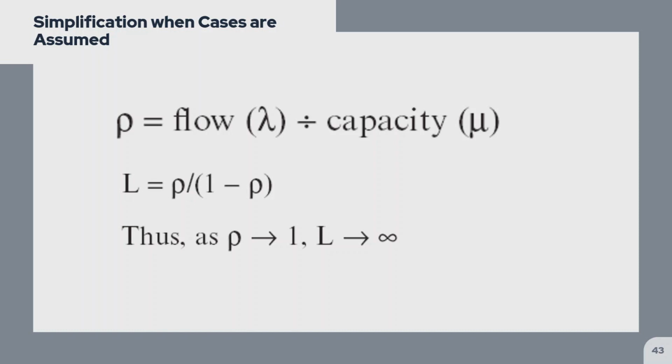On the other hand, within deterministic theory, the number of vehicles delayed depends on the difference between capacity and demand. It does not take into account the statistical nature of vehicle arrivals and departures, and seriously underestimates delay, setting it at zero when demand is less than or equal to capacity.